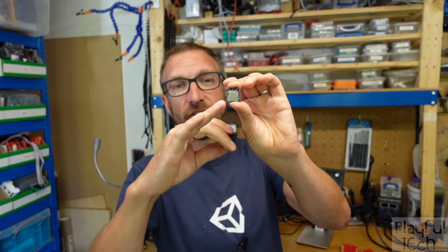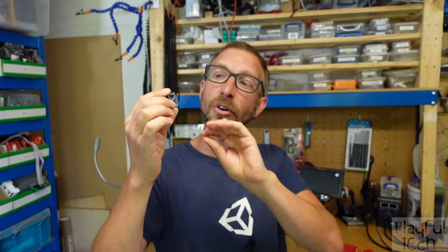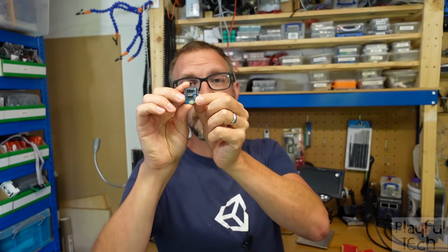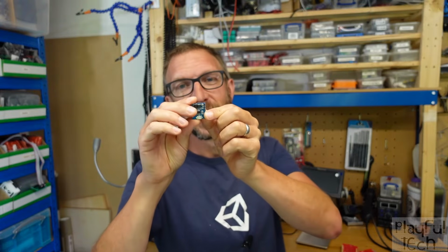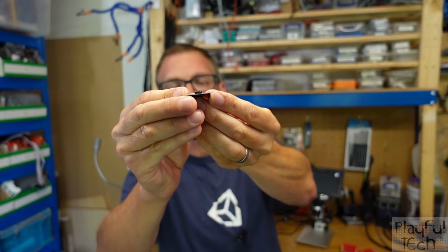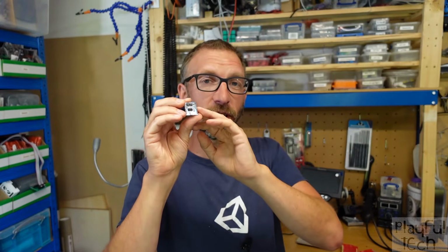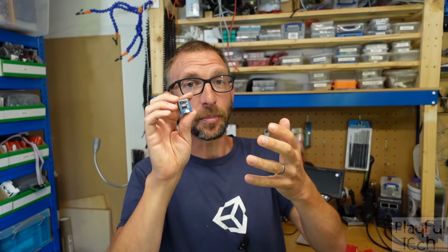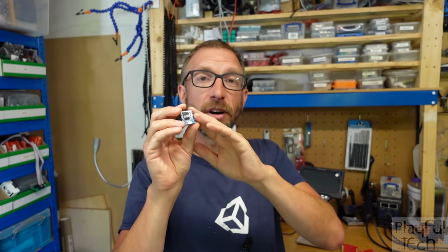Now, one key difference compared to the DF player is that instead of having an SD card reader, you store the audio files on an onboard 4 megabyte flash memory chip. That's actually really easy to do. There's a micro USB socket at the base, and when you plug a USB cable from your PC into that socket, it gets recognised as a USB storage device, and you can just drag your WAV or MP3 files onto the board. You don't need to install any funky drivers or anything like that.